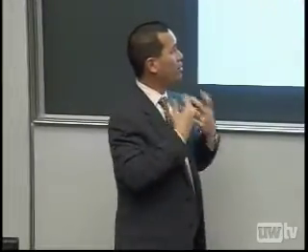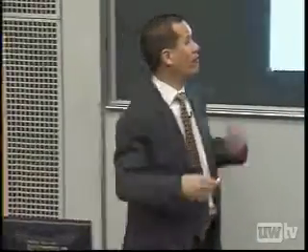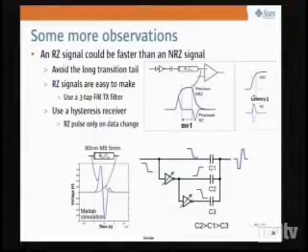If I could add the complexity of making it return to 0, I may be able to gain something. I'm able to run it faster, so I might have improved bandwidth as shown here, or perhaps better latency. The latency is better because my wires are already equalized. They just need to split. They don't need to cross first and then split. So if I can make it return to 0, which is more complicated, of course, I may reap a couple of benefits in performance. All right?